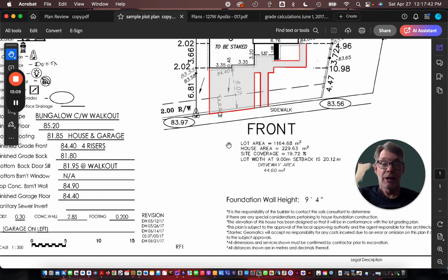We're super deep. So when you're being daring like that and going deep, you have to be aware of where the sewer is so that your wastewater will flow into it. Again, just an awareness thing for a professional to handle. And once in a blue moon, you hit a situation where the sewer is not going to cooperate. It's too high, so what does that mean?